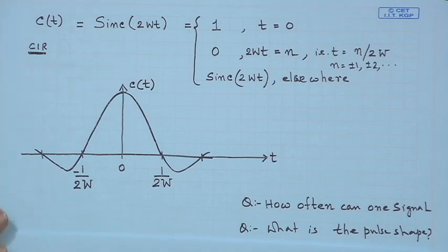Before we proceed, we would like to highlight that if we are considering an AWGN channel, that means we are taking infinite bandwidth. Generally, we have taken the power spectral density to be N naught by 2. But of course, we have also studied situations where we consider the passband with a certain bandwidth W, and we did consider narrowband passband processes. So, do not get confused with that. Generally when we take AWGN, we mean a signal with infinite bandwidth. Otherwise, we would specify the situation. What we have seen here is that instead of taking infinite bandwidth, the moment we restrict the bandwidth, we have an impulse response which is not an impulse, but a sinc.